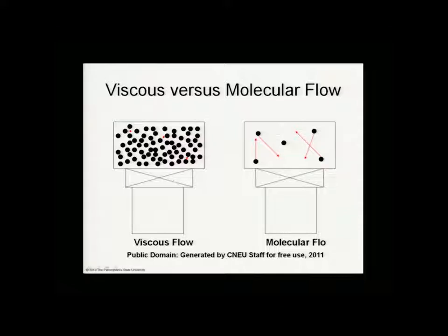Okay, what do we mean by that? Well, viscous flow means that we've got enough molecules around that the interaction among the molecules is important. The viscous forces between the molecules are a fancy way of trying to account for the collisions that the molecules suffer on the sides from other molecules. We call that viscosity. But really what's causing viscosity is the collisions, the interaction among the molecules. And so that's viscous flow, where these interactions are very, very important.